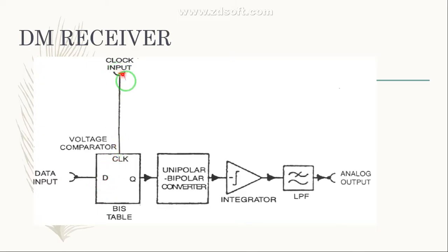See, this is the receiver clock, and it is delayed by half a clock period with respect to the transmitter clock, right? This has been done so that the data from the transmitter may settle down before being latched into the receiver flip-flop.